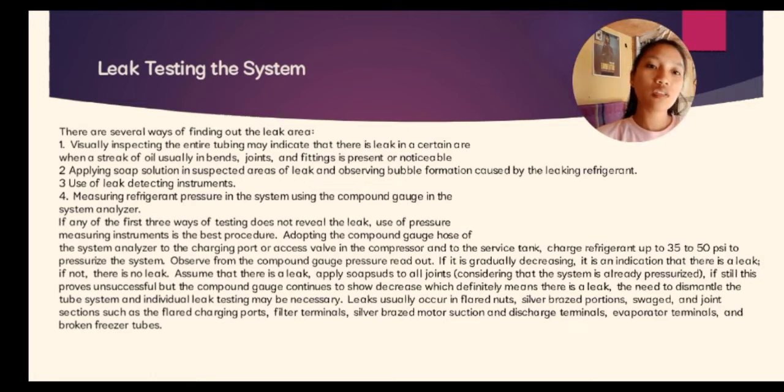Assume that there is a leak. Apply soap to all joints, considering that the system is already pressurized.